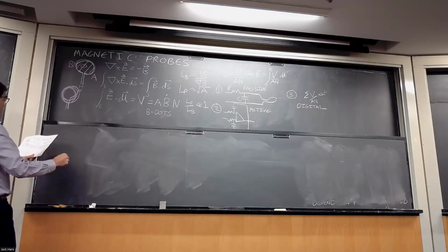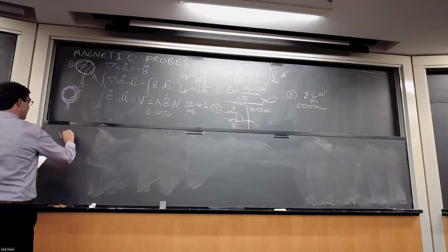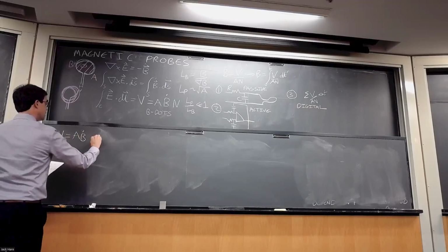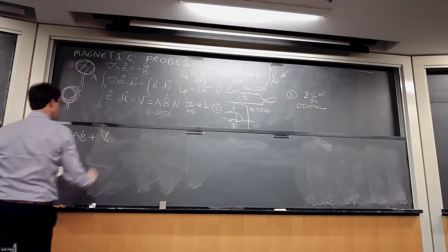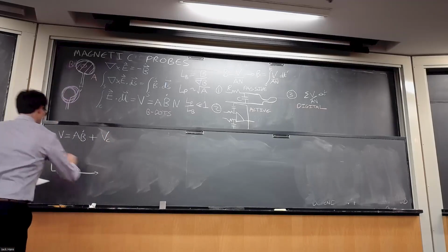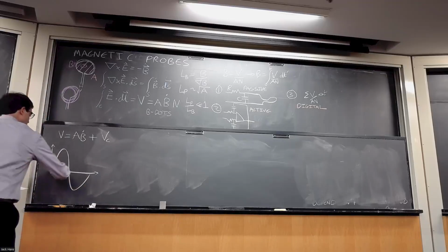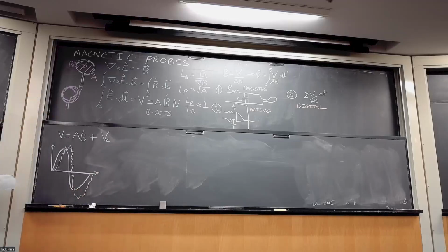So you may end up having a system where you have a loop which has a voltage on it, a B dot, as you expect, but there is also some other capacitively coupled signal like noise. So your signal would just look like this, but on top of it, you've got some other noisy signal that corrupts it. And as you start integrating this up, it's going to make a bit of a mess of your integration.